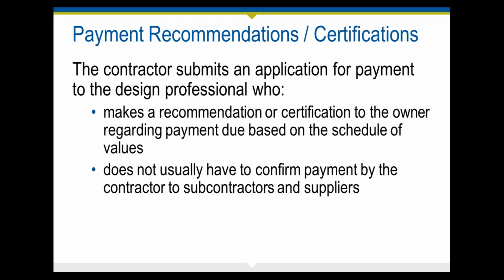One thing that you need to be aware of as the construction continues, and this is really not related to payment recommendations, is a responsibility for record drawings. The owner may want to have a copy of what the installed construction looks like. Oftentimes, you may have that responsibility. What you don't want to be responsible for is to call them as-built drawings.